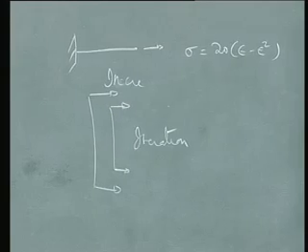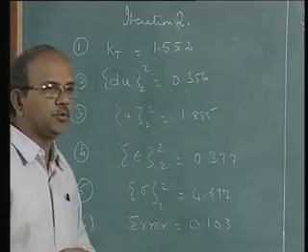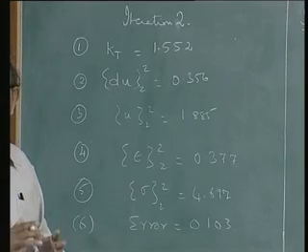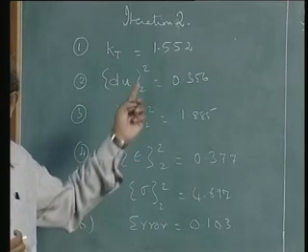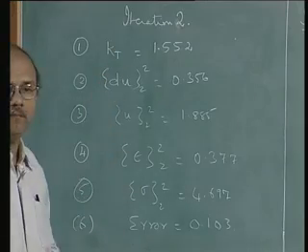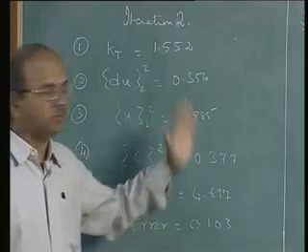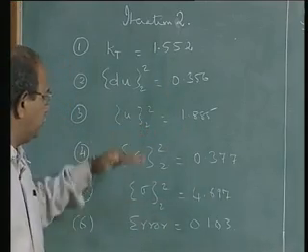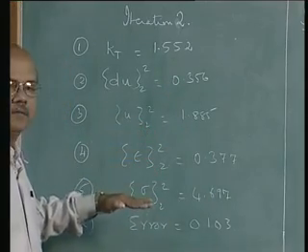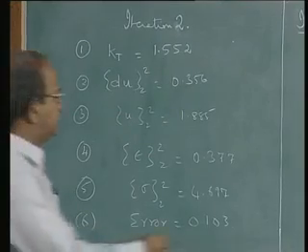So I have calculated already the tangent stiffness matrix, then du2. Note that du2 is this increment in u for this particular iteration. Sigma of du's was the ones which gave us delta u. Then I calculate the u, epsilon, sigma, calculated the error. The error has obviously dropped.